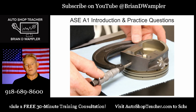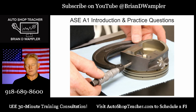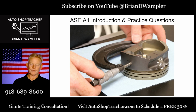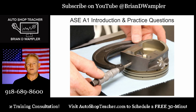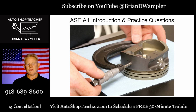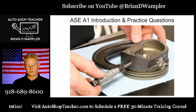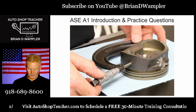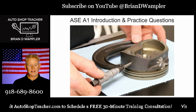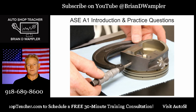This large part of the thimble, yes, you can turn it there where this technician is when you're making massive adjustments. Let's say you're moving this thing 1/4 of an inch, get it down to whatever you're going to measure. But then as soon as you start getting close, the fingers should be out here on this end portion of this micrometer. That is called the thimble, or as my auto shop teacher clear back in 80s high school auto shop used to call it, the great equalizer.